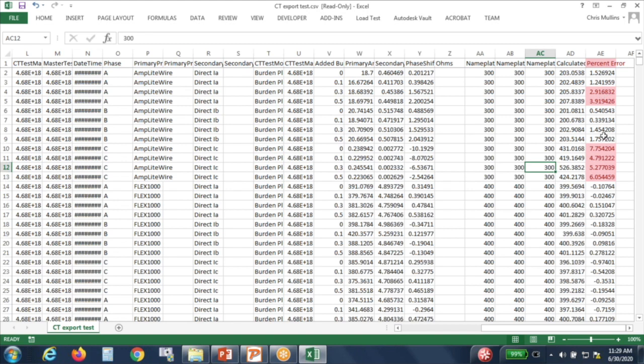So that puts me into troubleshooting mode. You know, as Jones likes to say, look at all your tools. This gives me a symptom, right? So I've got pretty bad percent errors on this CT, but what could be causing that, right? And then I start looking at, okay, I know the rules of a CT. So if a CT is below its nameplate, or below 10% of its nameplate, it doesn't have a stated accuracy anymore. So what can I do now?